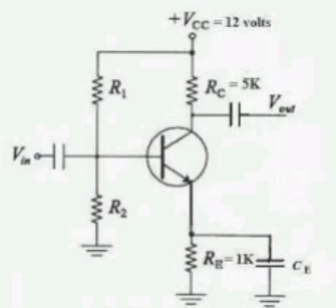The photocurrent density JL equal to 20 milliamperes per cm². Calculate the open circuit voltage of the solar cell at T equal to 300 K. Assume Ni equal to 1.5 × 10^10 per cm³.